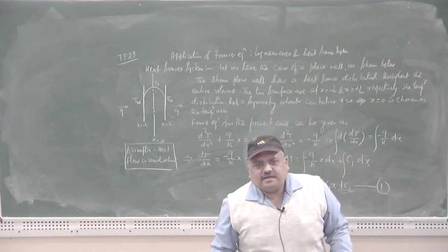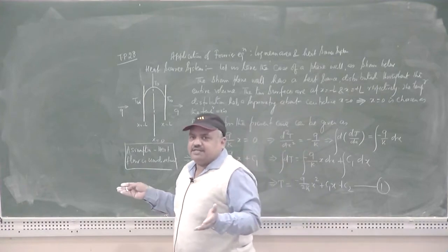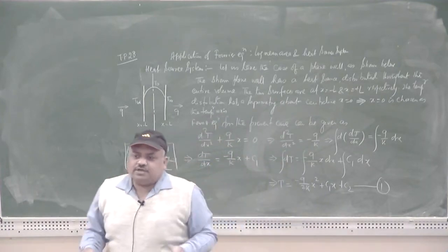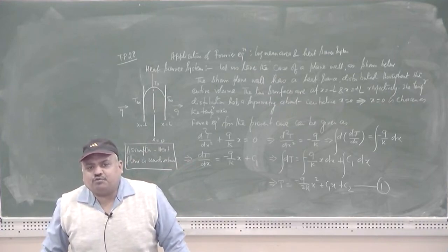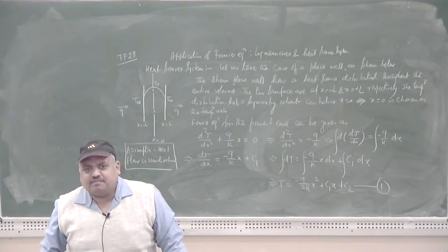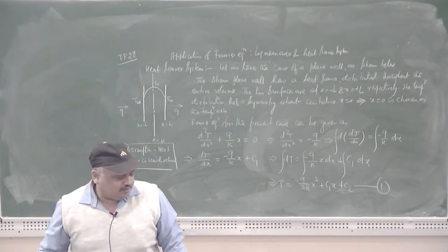Because I am considering the heat flow is taking place in only one direction, that is the x direction, the heat flow along the y and z axes is supposed to be insignificant, henceforth a 3-dimensional system may be converted into a 1-dimensional system, assuming that the heat flow is unidirectional in nature.